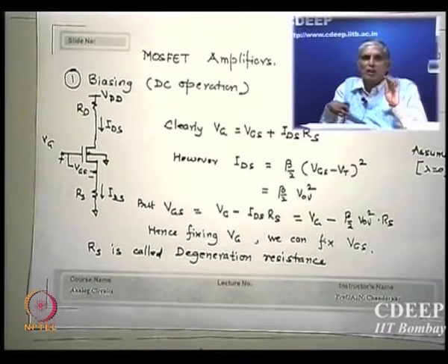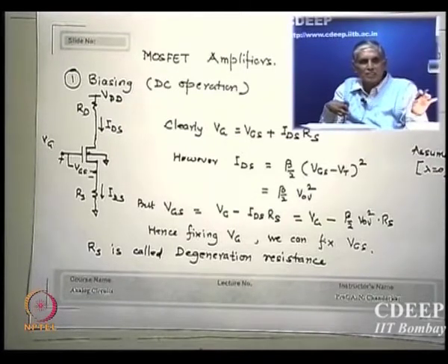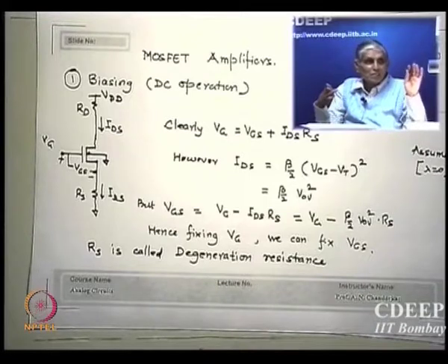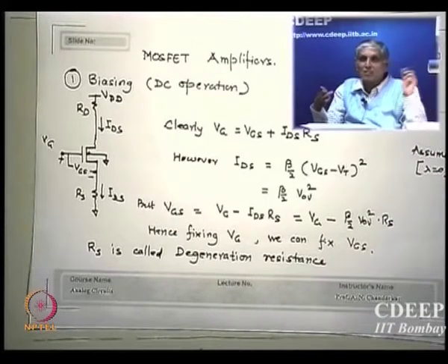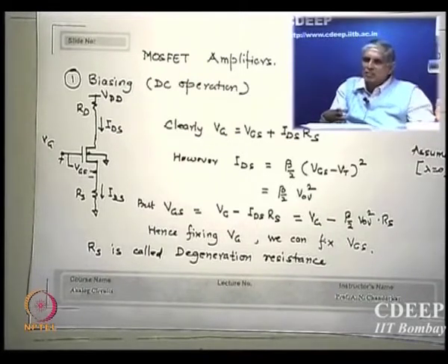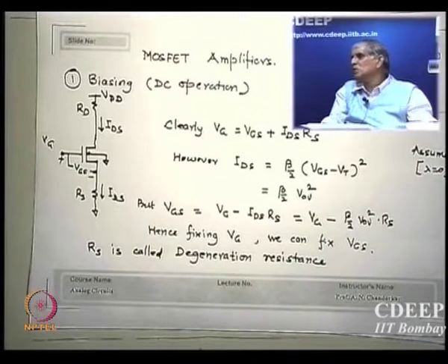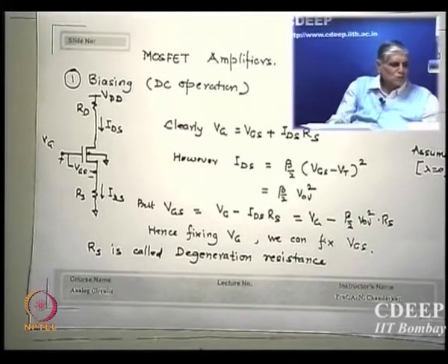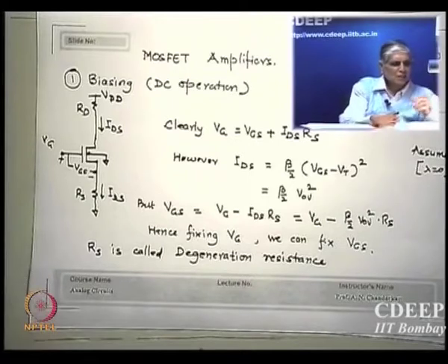If it is stated, then you will have to evaluate things. At least what things will you have to evaluate if VSB exists? The capacitances, those are direct functions of substrate bias. Yesterday we did that, isn't it? Otherwise, for this biasing case, we need not worry because these are DC cases, and capacitances do not play any role. So we just look for DC biasing.